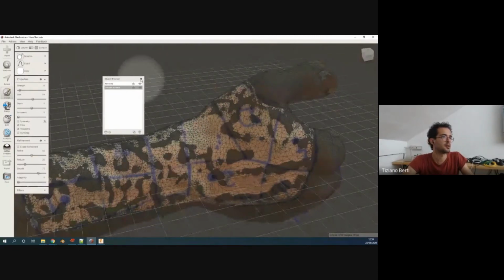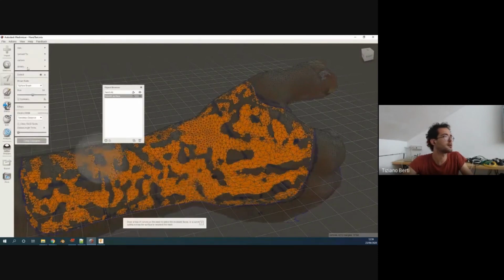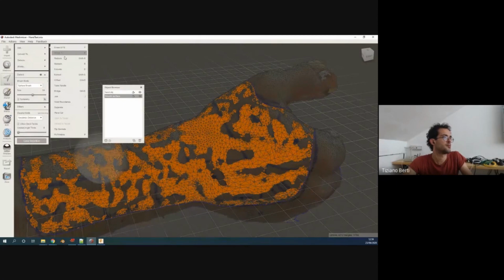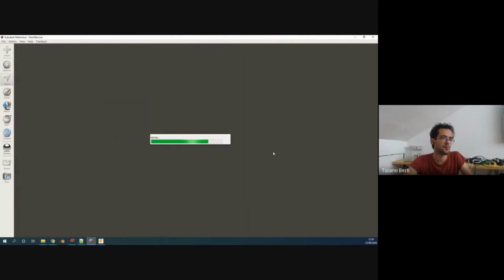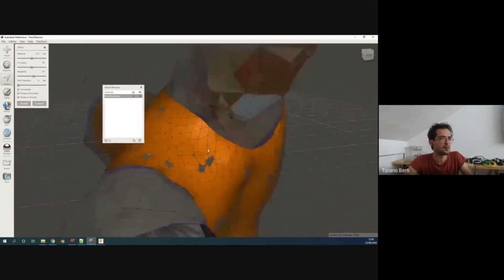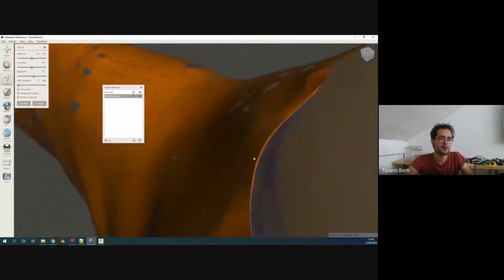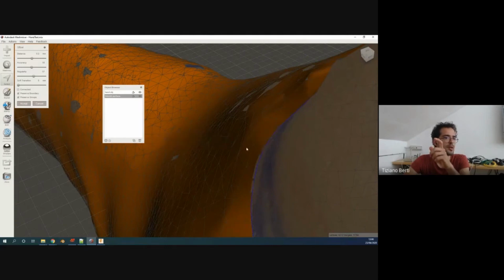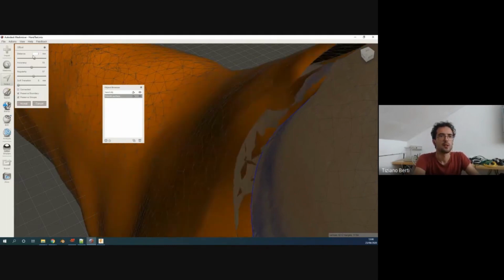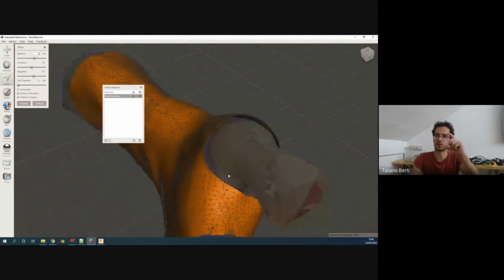Just after that, we can do an offset. So we can go to select again, Command A, select everything, edit, offset, and we want to make an open surface. So I just unclick connected. We'll make a second surface around 2 millimeters in distance, let's say. So this will be the center surface of my brace, okay?